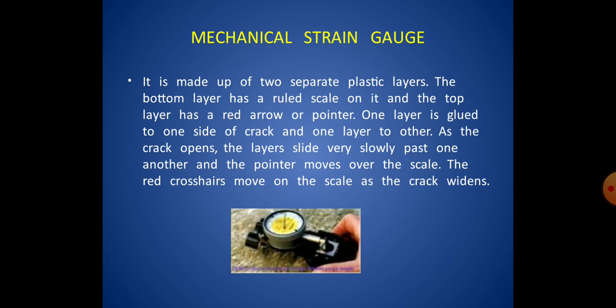The top layer has a pointer and the bottom layer has a marked scale. When we apply the force hydraulically, the component extends and the pointer moves on the scale. Hence we can measure the deformation or the strain from the scale.